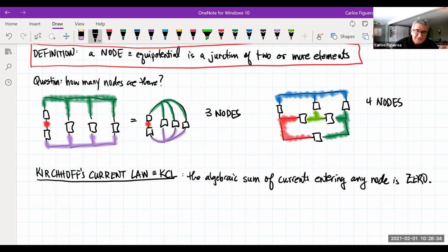Now it turns out that I don't really like that sign convention. A lot of textbooks do use it, but what does it look like mathematically? I'll show you what I mean. It says here that for all of the currents coming into some node, the sum of these guys is 0. So that means you need a sign convention. What this really means is the sum of the currents going into the node minus the sum of the currents going out of the node.